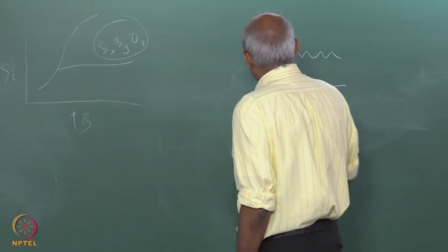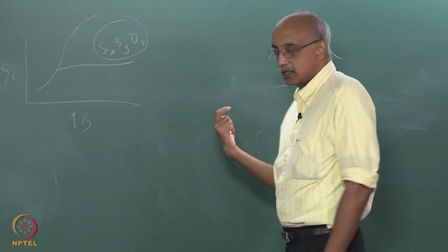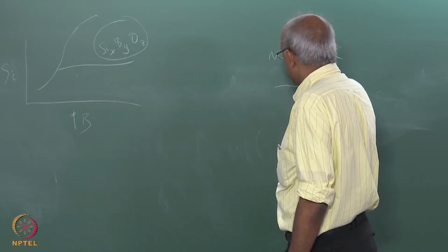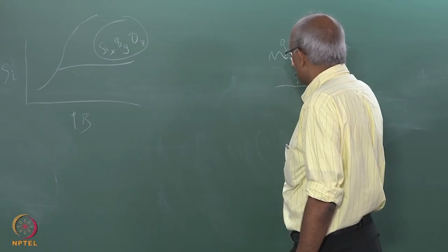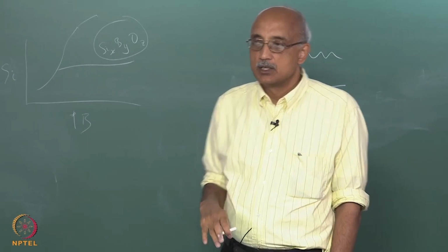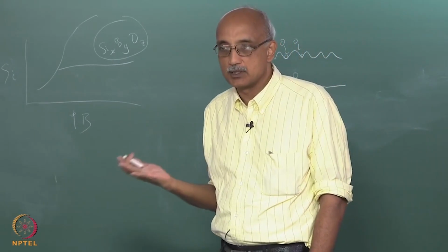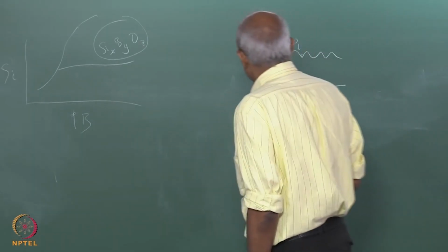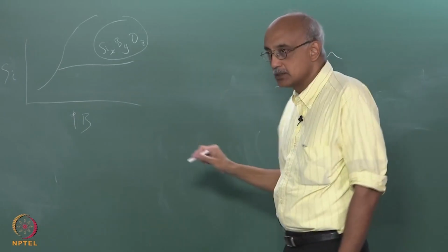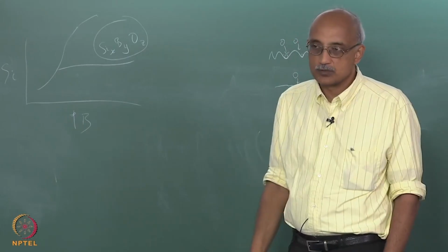For example, if the roughness asperities are larger than the arriving molecule diameter, then it is fairly easy for the arriving molecules to get captured on the surface. So, a rough surface will actually increase the sticking probability in such cases, primarily because it now provides a larger surface area for capturing the oncoming molecules compared to the smooth surface.